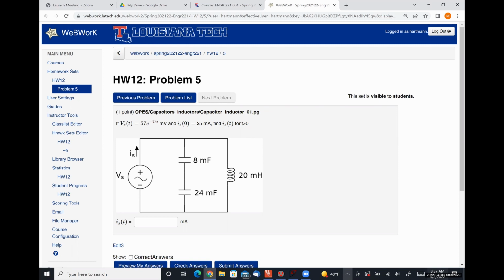So only specifically for a DC source do they behave in one particular way. They look like an open circuit. For any type of source that has any type of time variance to it, the derivative and integral based relationships that we developed today are the correct relationship. Davis, so that source was a DC current source, and basically being open circuit. Yep, absolutely right. You're 100% correct.